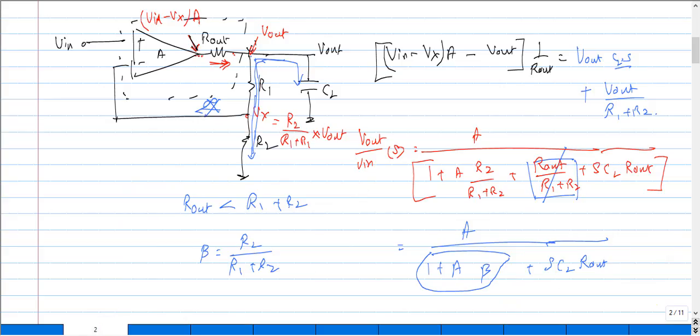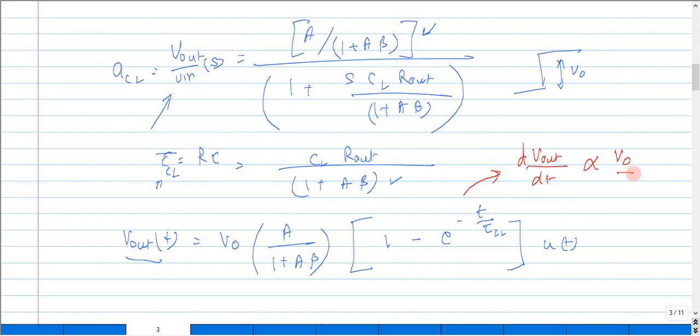Now the point here is, if I can follow this equation for any step input, or any magnitude of step input or value of V0, then the circuit functions as a linear system. But in case for a particular value of V0, which could be a larger magnitude, if the system can't produce an output which is rising at a rate proportional to our new value of V0, then the circuit is said to have a slewing property, or the circuit is said to be slewing. Basically, it is not following this proportionality, correct?